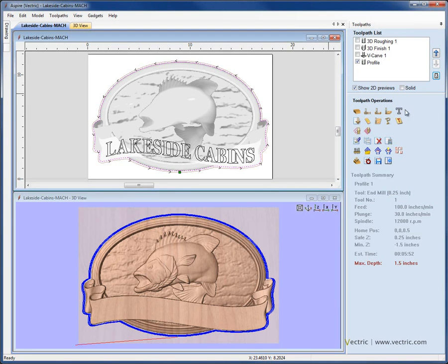Coming down into the toolpath operations, we have all the icons for controlling the toolpaths and for creating them. The first here is very important because this allows you to set up your material and your rapid clearance gaps. Then we have various 2D toolpaths along the top row here: profile, pocket, drilling and engrave. On the next row we have what are known as 2.5D toolpaths: V-carve, fluting, texture, prism carving, and then the automatic inlay tool for cutting out parts that you need to inlay into a pocket or for creating the pockets to inlay a part into.